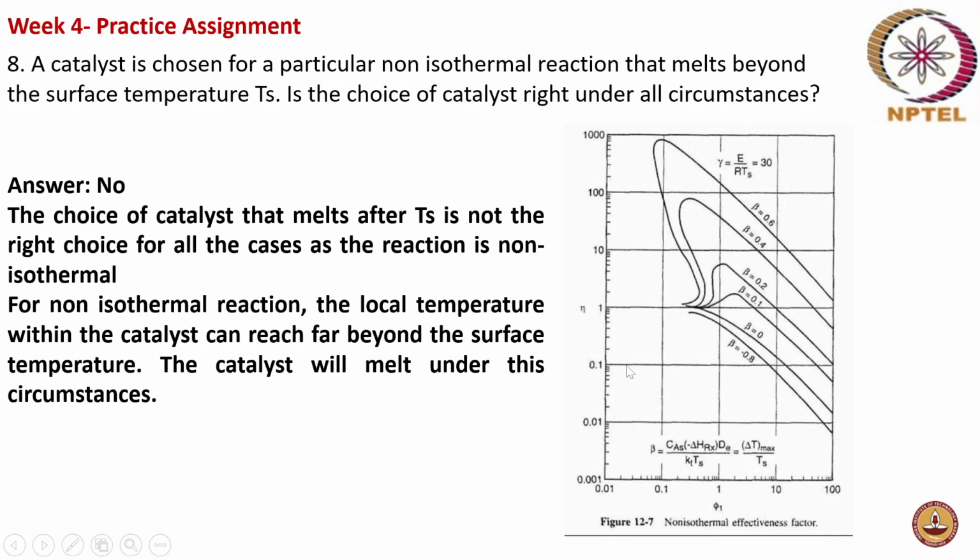Say for example, in this case, at point 1, you could see that it has two steady states. And there will be cases where there will be three steady states. So there might be some steady states which are unstable, and the system tends to shift towards the other. In this process, the temperature might shoot up, and also there is a possibility that the reaction goes runaway.